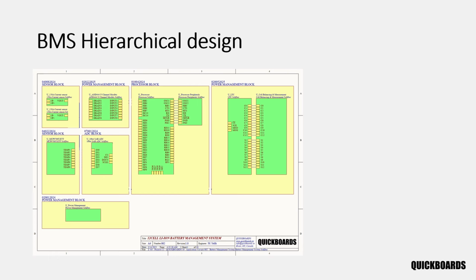The voltage outputs from the temperature and current sensors are routed to the analog to digital converter. The battery and charge relay drivers are connected to two general-purpose I/O pins of the microcontroller, and to enable communication between the microcontroller, the LTC6811, and the ADC, a Serial Peripheral Interface, or SPI bus, is used.